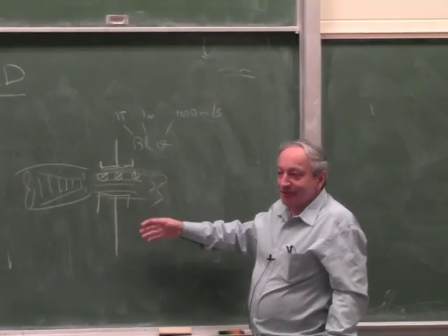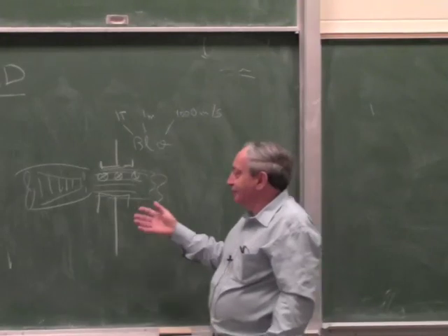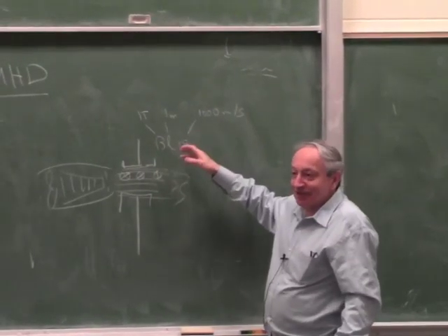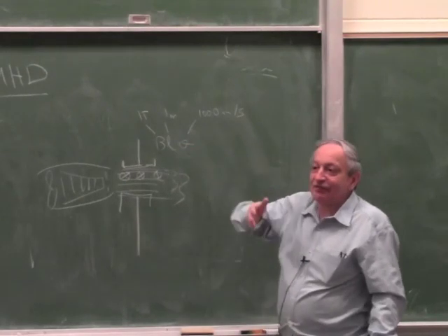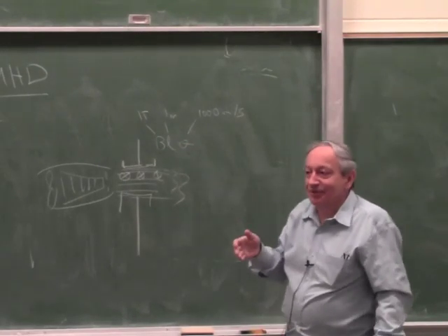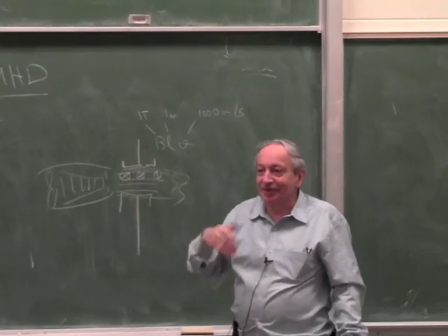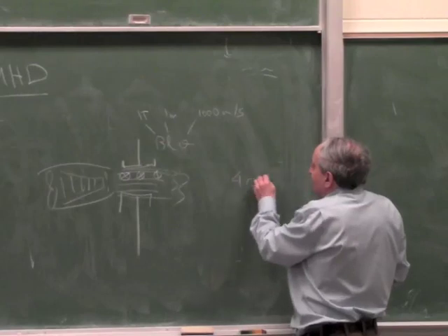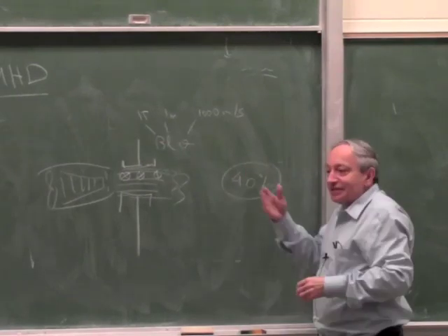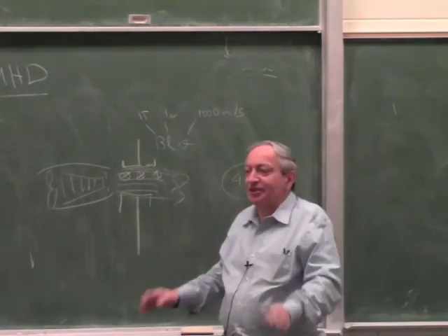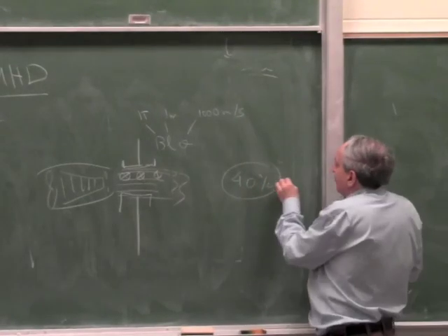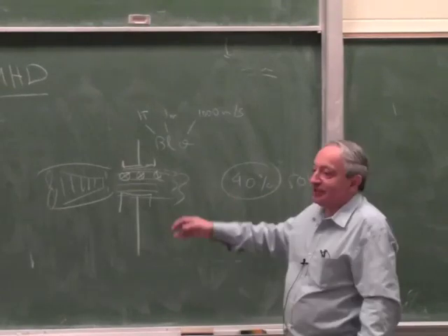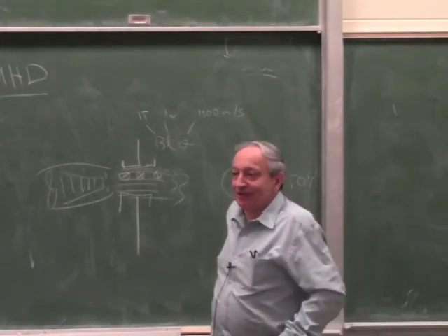Okay, and these people built this stuff, but in the end it was less efficient than taking this heat and running a steam turbine. The gold reference is a steam turbine, because you can always take the heat, boil water, and run a steam turbine. A single-cycle steam turbine is 40% efficient. You can do multi-cycles and all kinds of things, but a normal steam turbine is 40 to 50%. So the gold standard is 40 to 50% efficiency, and if you're not there, people lose interest very quickly.